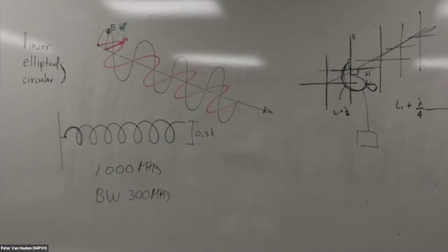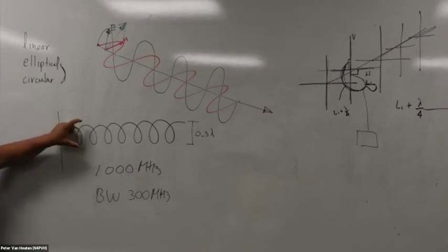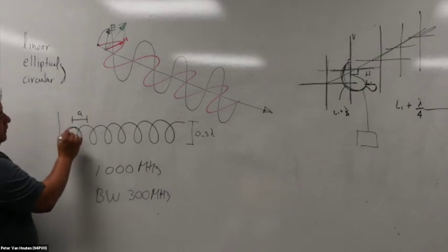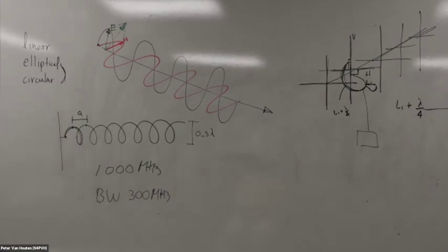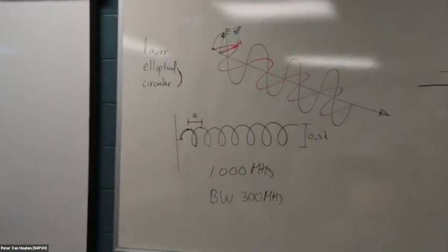There are curves to design these that, depending on the number of turns, give an optimal diameter, and also the step, or the distance between one turn and the next. There are several things there. Let's say this is the back of the antenna. If you wind that coil like this, it's going to be right-hand circular polarization, or the other way will be left-hand circular polarization.